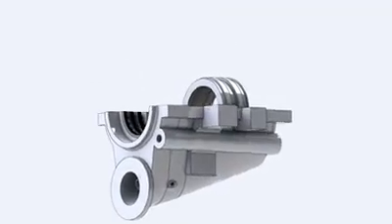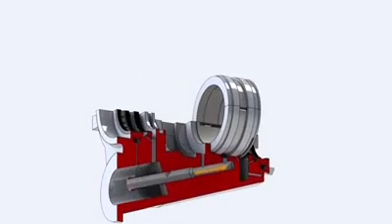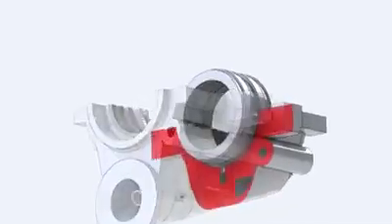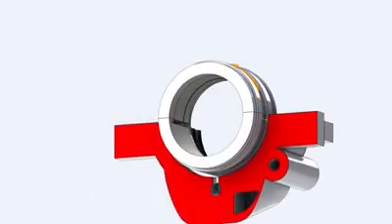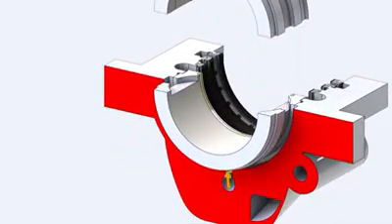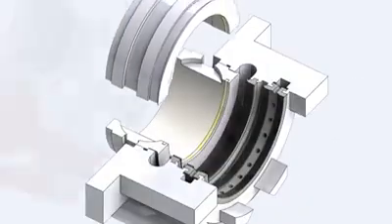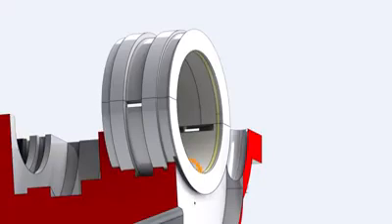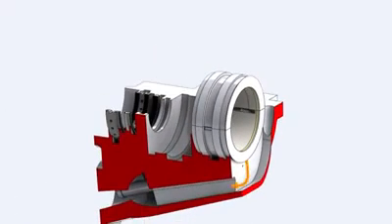For lubrication, oil is supplied through the oil feed pipe to a port in lower bearing housing, where the oil fills an annular space around the liner and is admitted inside the liner through 2 grooves machined at the horizontal matching edge. Oil is drained through the vertical drain slot at the bottom of the lower liner half to the journal drain cavity down to the oil drain piping.